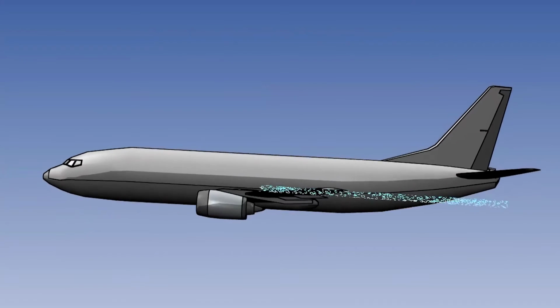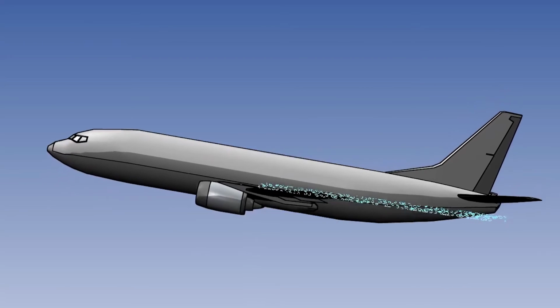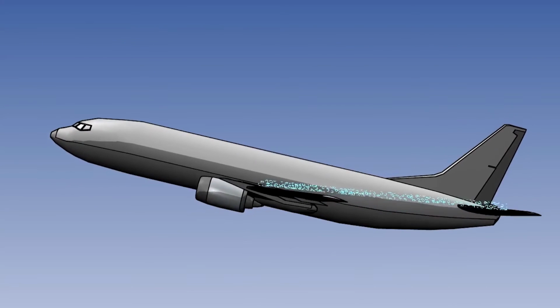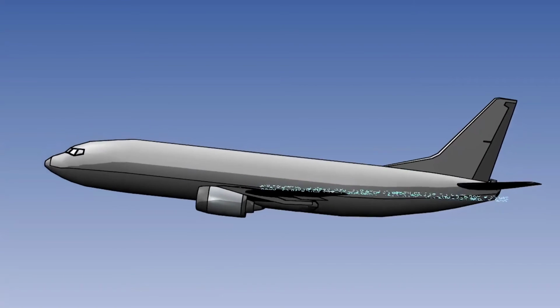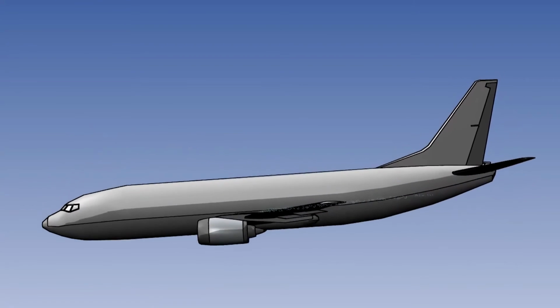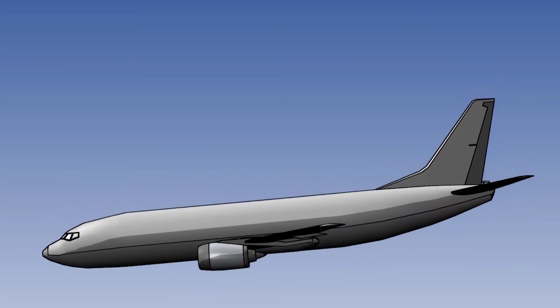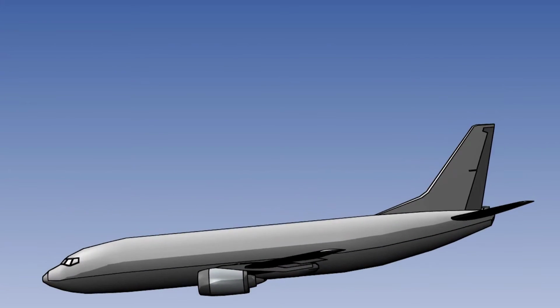If a stall occurs, either incipient or fully developed, the principal action that must be taken is to reduce the angle of attack below the critical angle to decrease the adverse pressure gradient. This action may consist simply of releasing back pressure on the control column or moving it smoothly forward until the wings are unstalled. Excessive forward movement of the controls would lead to an unnecessary height loss during recovery.